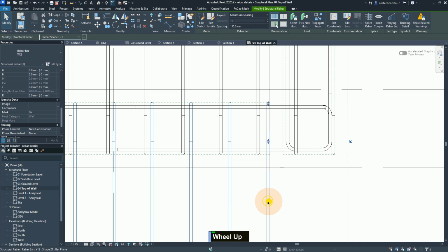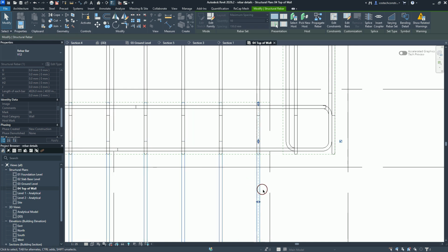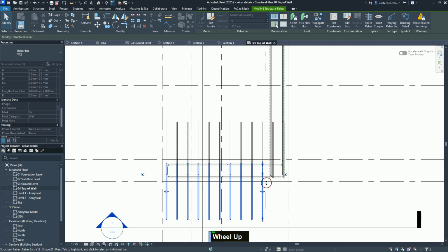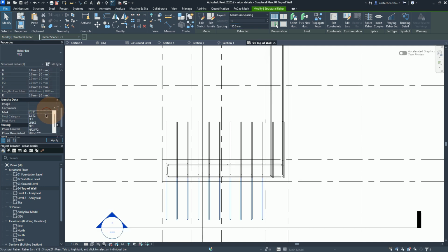So for example, I can select it from here, then snap it to the other Rebar set like that. So if we zoom out, we now have 10 as the quantity. So for this one, we are going to give a comment value of near face 1. So I'll come here to the comment, drop, then give a comment value of near face 1, then hit apply.